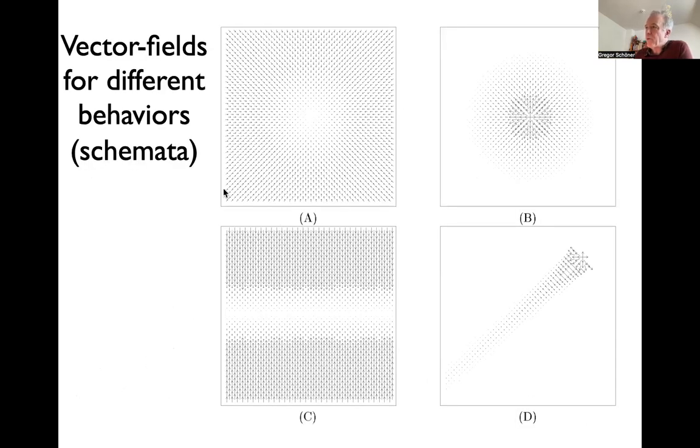And here are examples of how some of these behaviors could be implemented. So here, this is attraction to a point. This would be a vector field that keeps you on a path, a stay on path. You could have another one that moves you in the path. This is a repeller, an obstacle. This is actually a repulsion just from a certain direction. You can also have an attraction from a certain direction, which would lead to docking, arriving in a particular orientation at a target and so on. So a whole, they call these schemata, but they would be essentially more general forms of vector fields. Again, it's always the descent, so it's the transient that is the behavior. It's not an attractor dynamics approach in that it's not sitting in the attractor that generates the behavior.